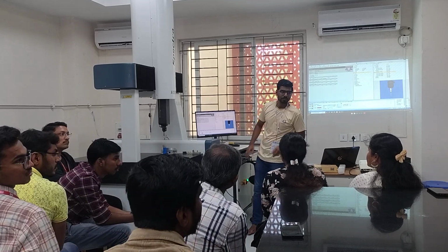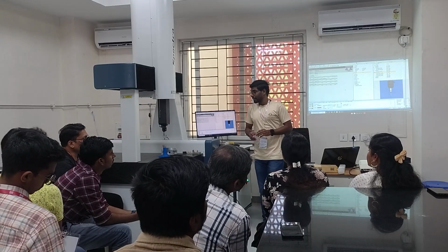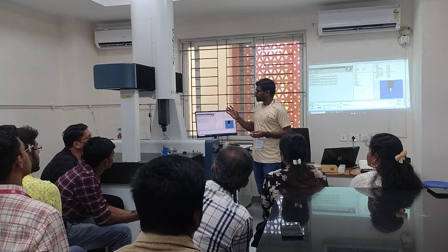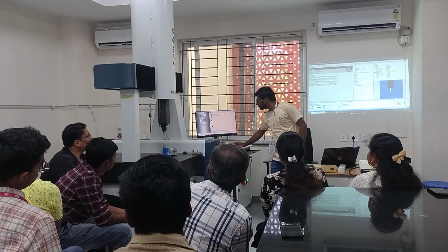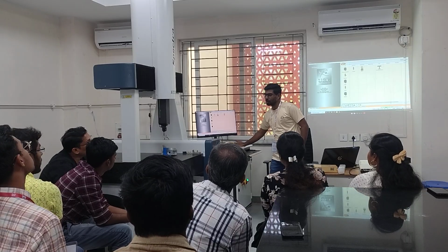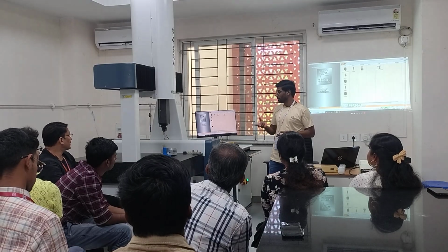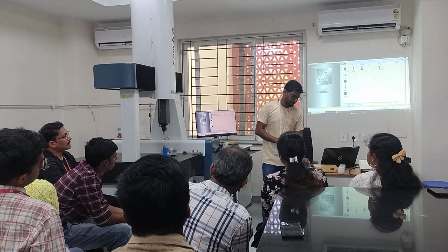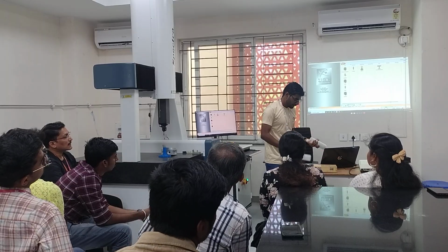There is no need to measure the origin whenever we perform this measurement. First of all, there is a homing option. When you do it, automatically it will go to the home. So after that, there is no need of any kind of measurement. But yes, calibration is required.